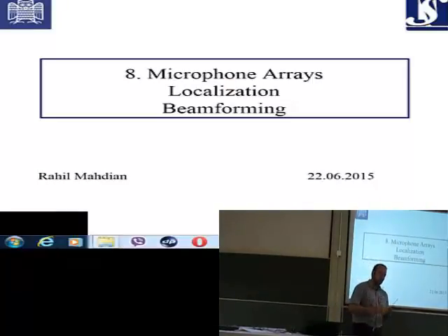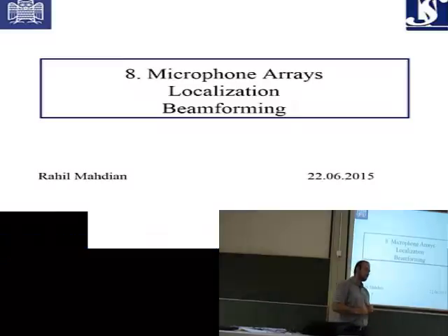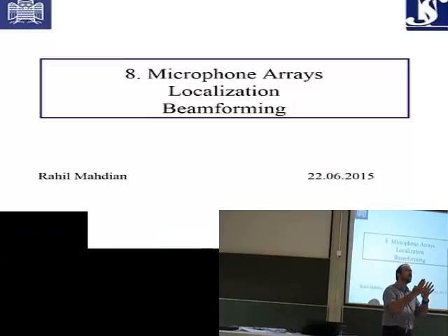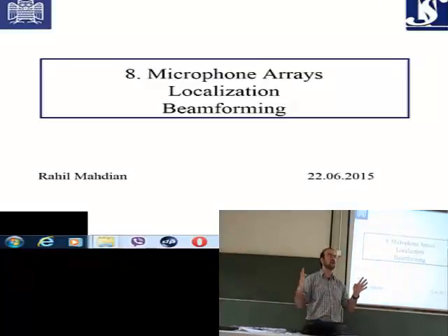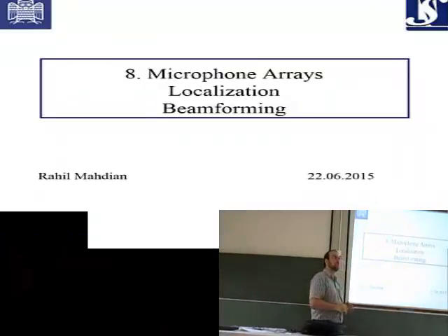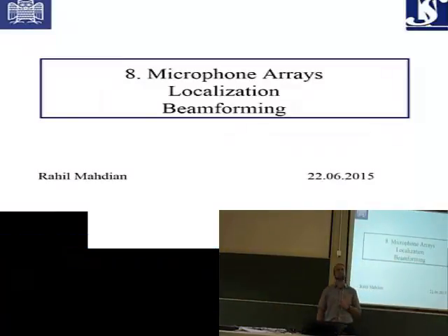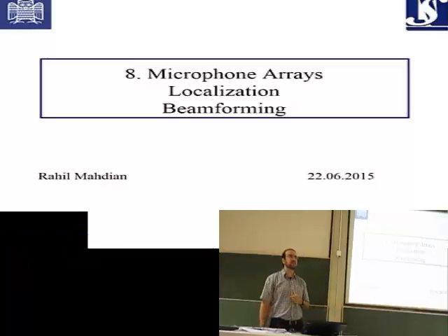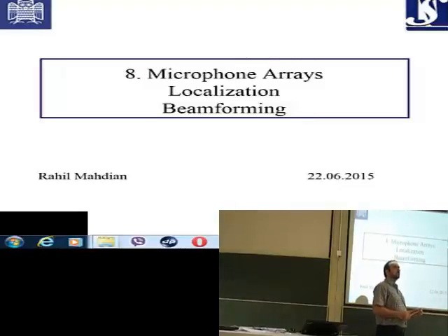But the point is that when you cut the data into small chops, you are reducing the frequency resolution of the data at the cost of time resolution of the data, to see more localized data in time and sacrificing the frequency components. But the components which you are sacrificing are probably and hopefully not that important.